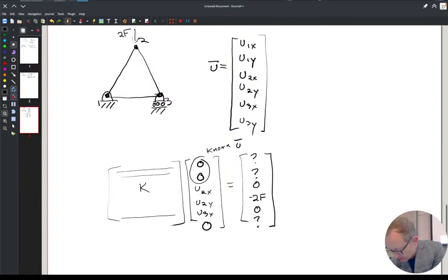So the first 2 rows, the last row, and then those first 2 columns and last column is all stuff that I don't need to solve for. So by grabbing that middle part of K, now I'm plugging in boundary conditions, where in those spots I have a known displacement that's already fixed.